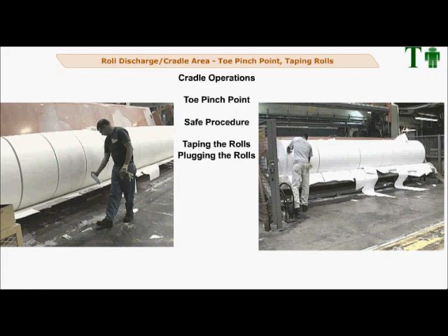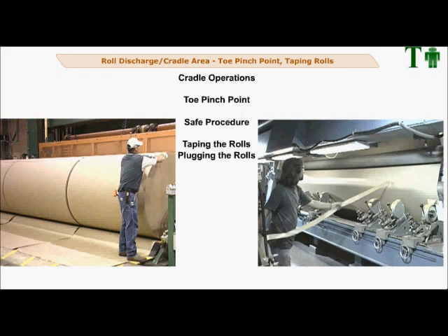The cradle and the rolls must be stopped before taping any finished rolls or plugging the end rolls. Never stand in front of a moving cradle. Each mill should identify the safest method to use for taping rolls at their mill.